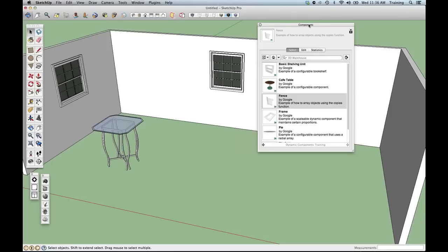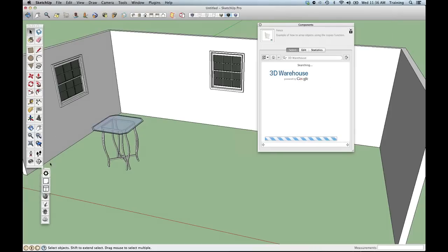Now, if you go into Architecture, you can see that there are actually cabinets here, and they're very basic ones. If you're just doing really basic space planning, they'll work okay, but if you really want to design a good, detailed kitchen, I think my plugins will work better. So the way the plugin works is you download it, and it will bring up this little toolbar here. And you get 3 buttons. You get the gear button, which allows you to log in with your account. You get the door button, which allows you to swap doors out, which we'll talk about later, and you get the cabinet button, which allows you to get cabinets.